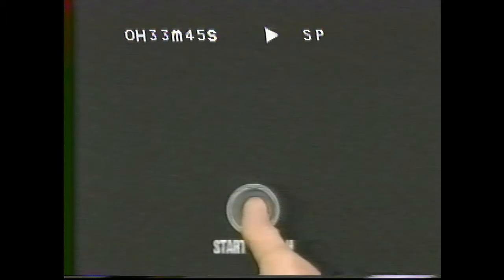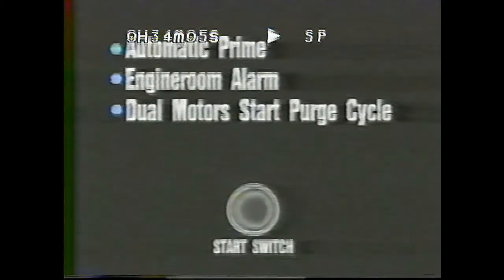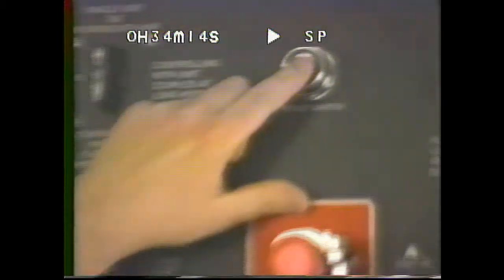Push the engine start button and hold for about 2 to 3 seconds. The locomotive's computer will automatically prime the fuel system. Then, it will sound an alarm in the engine room to warn that a cranking cycle is about to take place. The engine's dual electric starting motors will start the purge cycle and crank over very slowly for about 6 seconds. Then, 2 air motors engage the flywheel to bring cranking speed up quickly. All this with just the push of a button.